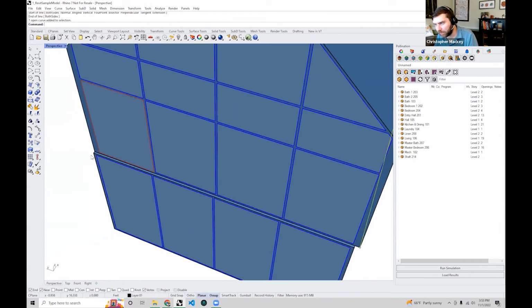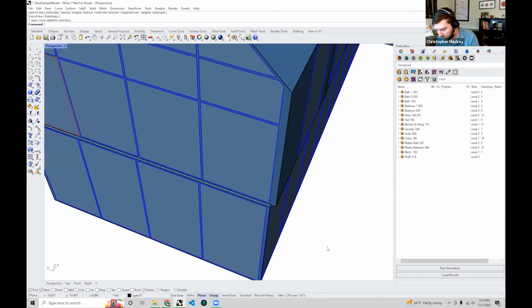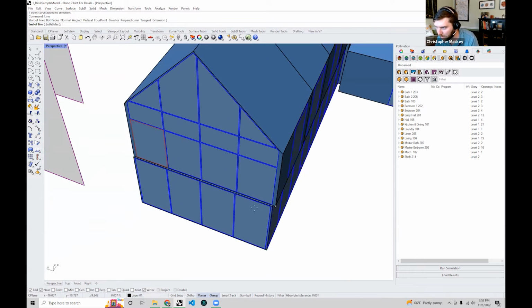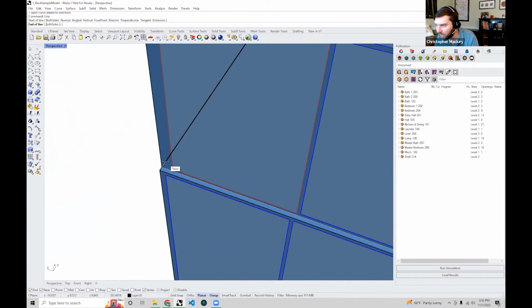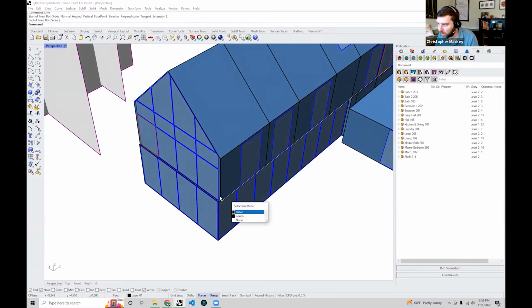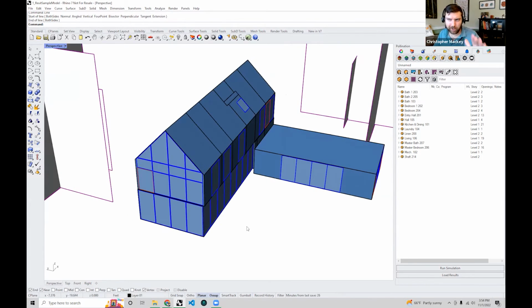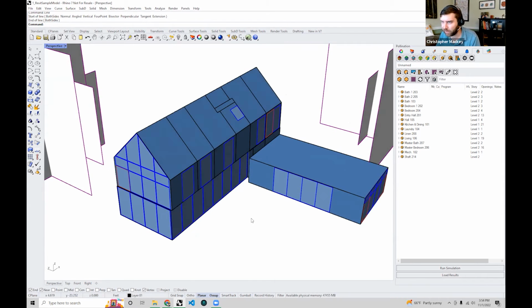I want probably something similar on this axis here, because these two are also just off by a little bit. So I'll draw another Rhino line, and I'll click from here. Maybe I'll do shift and then tab again, so I'm snapping to this world y-axis in the Rhino scene, and I'll make it go to the end there. Once I have these two curves drawn, I have what I need in order to align the model to these curves. So I don't know, does anybody need to see the line drawing again, or have any questions on that?